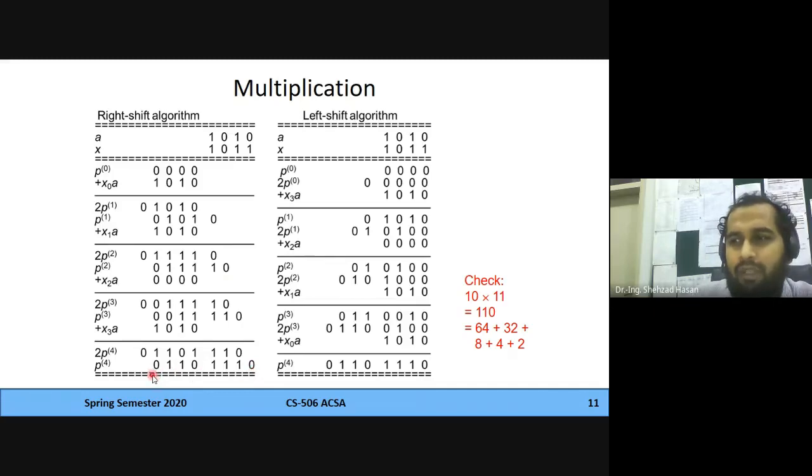Because if you come to the hardware part, you're going to see we have got 8 bits for product here. So these are the 4 bits over here, and this is the extra bit that we have shown, as I've mentioned, that it's going to just tell you what's going to come on this side. So you can just imagine that this bit is not there, right? So what you have obtained at this point is a 7-bit number. You finally have to shift it to make it an 8-bit number, and this is going to be your final answer.